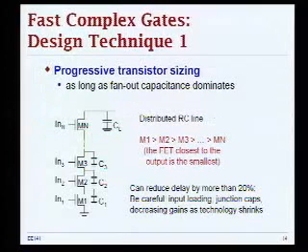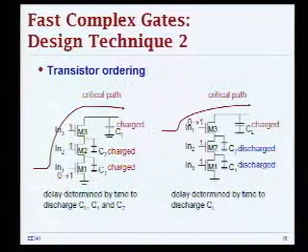This is what we also discussed. You have progressive transistor sizing. When you have a long stack, you would want to make M1 the biggest, and then you decrease the size gradually. This is a good technique, but it can't really buy you much in delay, maybe 10% or so. So just be aware of that.